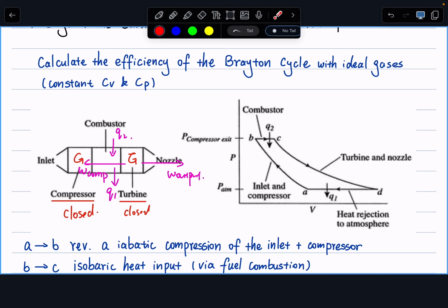So it's a nice sanity check. And now we're ready to calculate our efficiency. That's pretty much just this whole thing. So Cp, TA minus TD plus TC minus TB over my Q2, Cp times TC minus TB. My Cp cancel out, we only have temperature left in my efficiency.